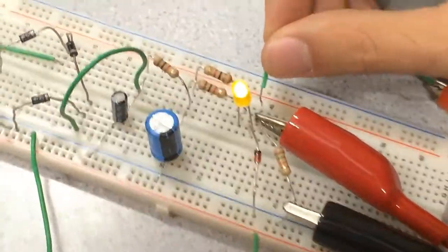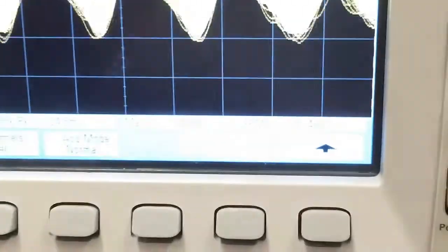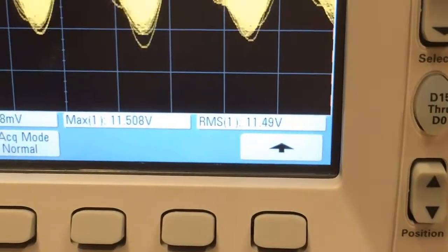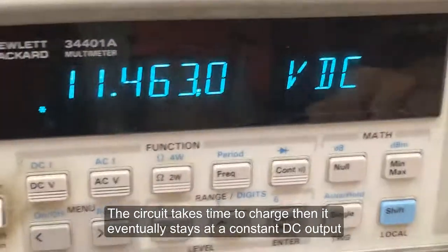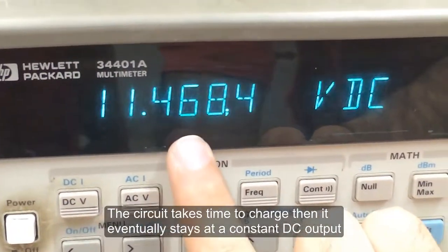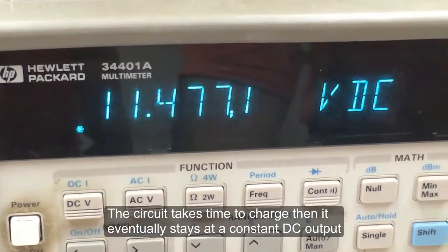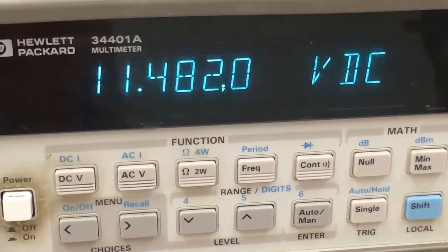When we connect it on the oscilloscope, we can see our RMS value. Yes, on the oscilloscope it says close to 11.5, and that's not too much. It's just 0.5 under 12 volts, and the DMM says it's around 11.46 volts, or close to 11.5.